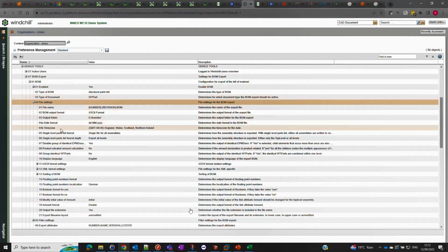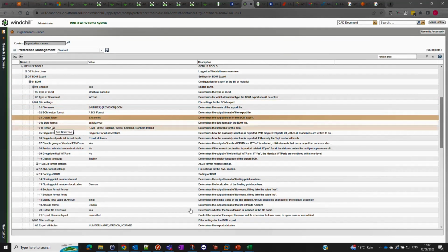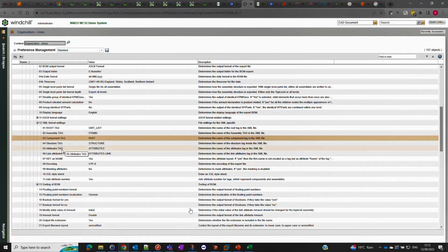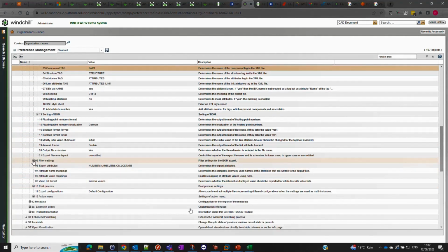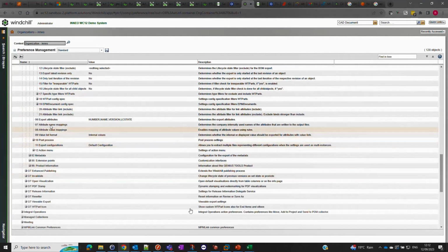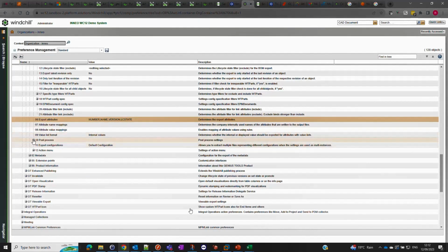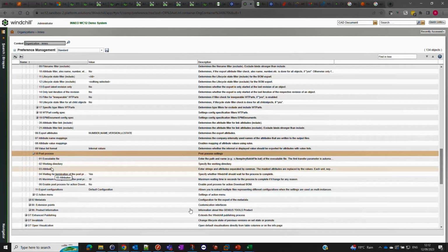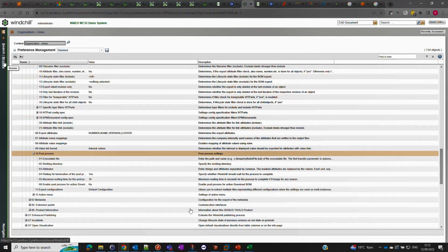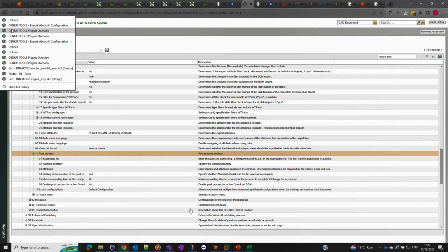For example, the BOM export, and here we can do all kinds of things like set where files are exported to, how the XML file is formatted, all kinds of tags inside of that. We can do things like setting filters, how is it triggered, what kind of attributes we want to include, and even we can extend it to do things like post-processing, so you can write additions on top of this to do post-processing of the files before it gets sent onto a third-party system.